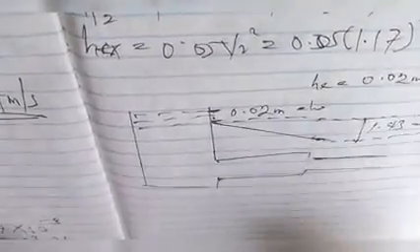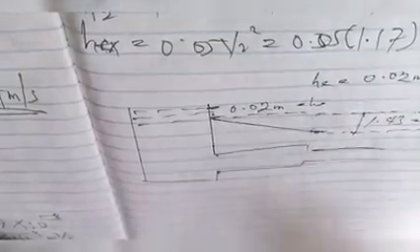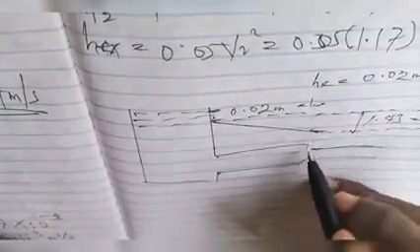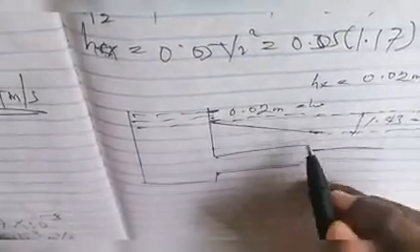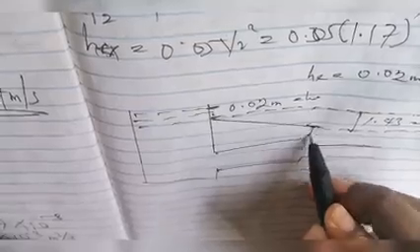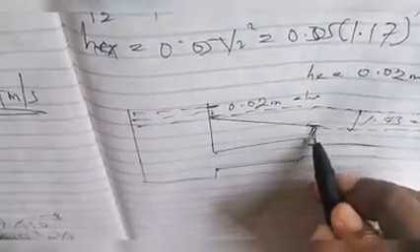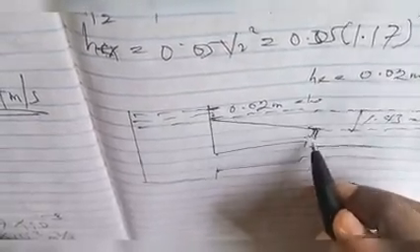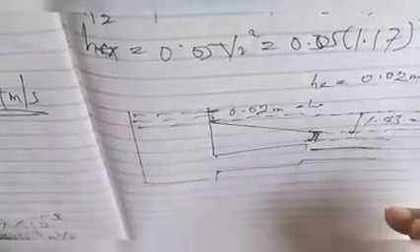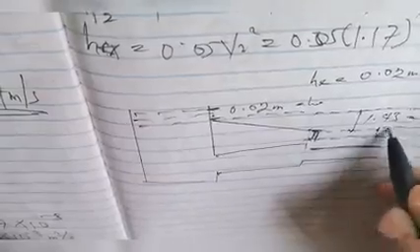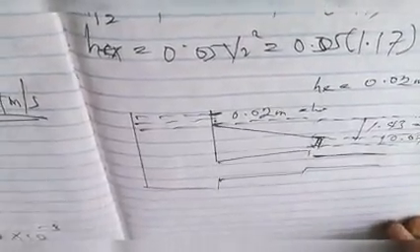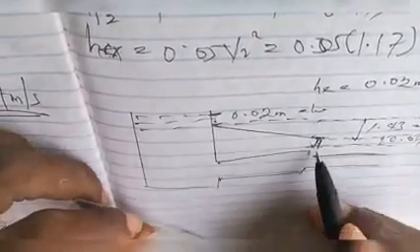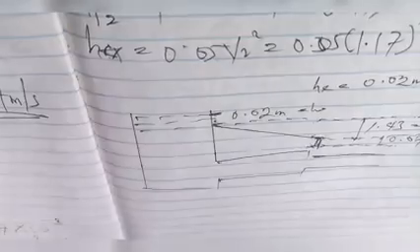So you also measure 0.07 down to the contracted region, which is somewhere around here. So you also trace this. So this height is 0.07 in meters. This will be the head loss due to sudden contraction.